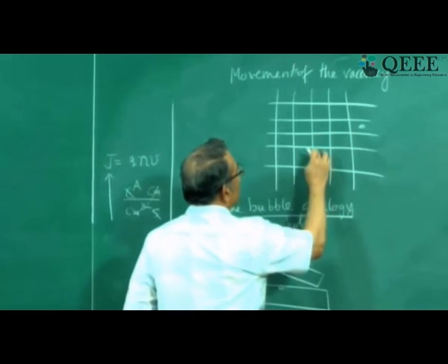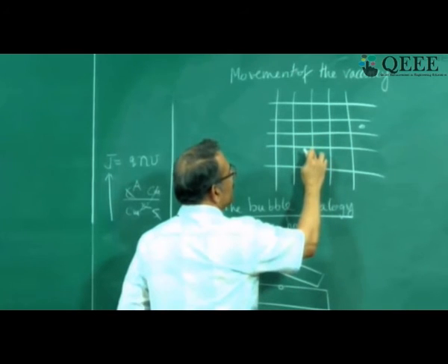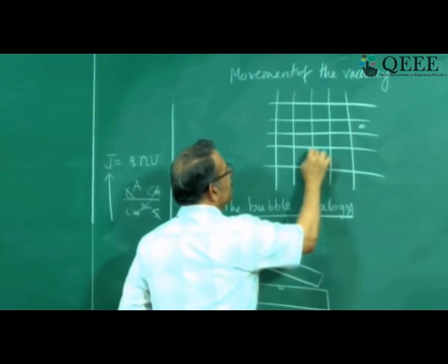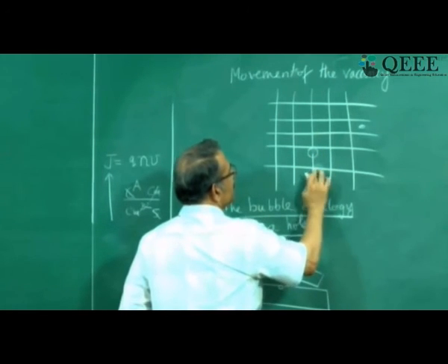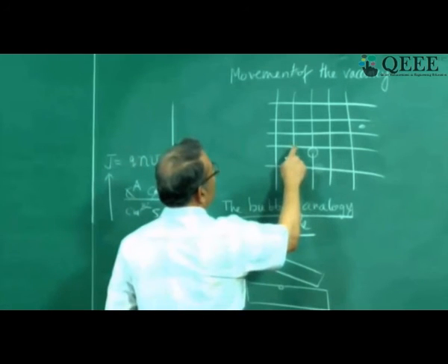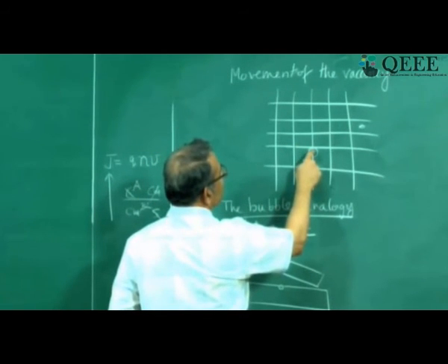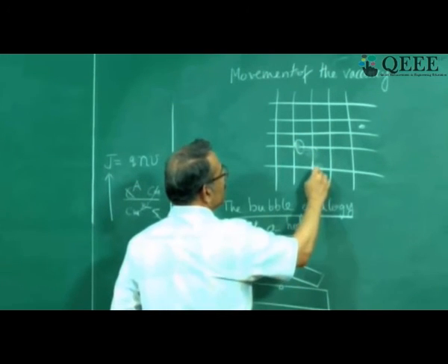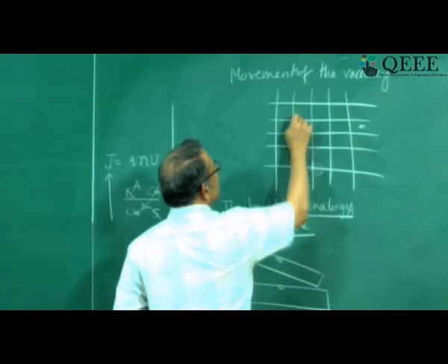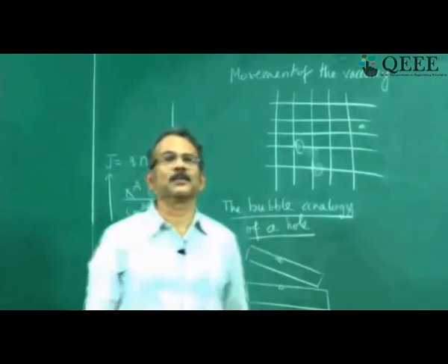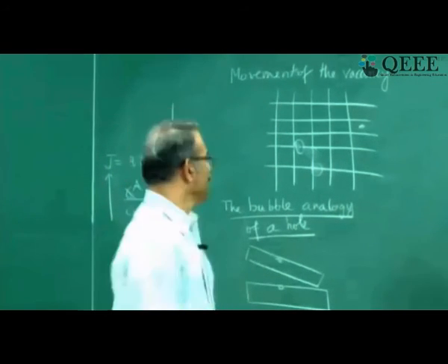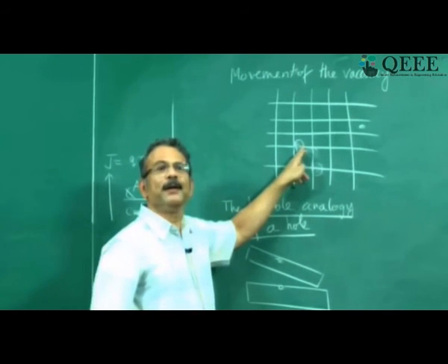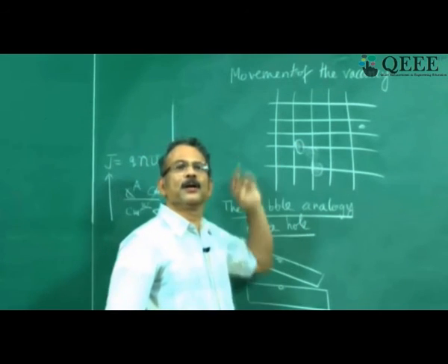What can happen is an electron from this bond, for example, can get into this vacancy, so that this bond will be filled up and the vacancy would have moved here. Then it can happen that an electron from here can get in, right, and the vacancy will move here and this bond will be established. That is how the vacancy has sequentially moved like this via the various atoms, right. The same as the liquid getting into the bubble. Similarly, a bonded electron can slip into the vacancy.